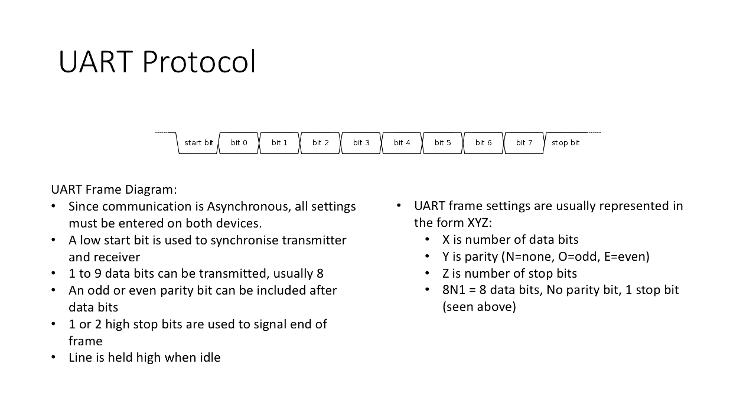An example is somebody interfacing a couple of sensors using I2C with a microcontroller. But when you are using I2C, the problem is it should have different addresses, because these had the same address. That is one of the common issues I see when you interface it, and some of you are laughing because they are doing capstone with me. If you got different addresses, then you won't have this issue. But you can get rid of it by using a mux or something. Anyway, I'll come to I2C, then I can discuss.